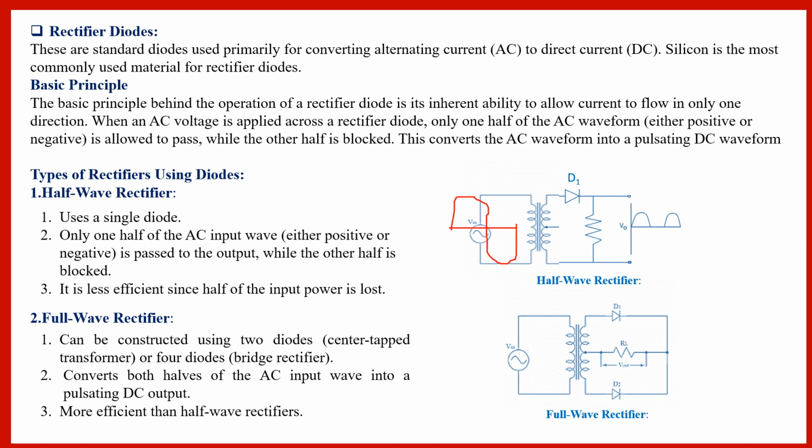So if we talk about the half wave rectifier, basically what happens in half wave rectification is that the rectifier conducts current only during the positive half cycles of the input when the AC is applied. The negative half cycles of the AC supply are suppressed. During the negative half cycle, no current is conducted, and hence no voltage appears across the load. Therefore, the current always flows in one direction through the load, after every half cycle.